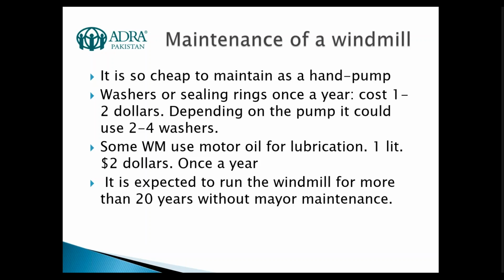And also the windmill can last more than 20 years without major maintenance. And the maintenance can be done, as we say, by the community as well. It's very, very cheap to maintain one of these windmills. Maybe from time to time only painting the windmill if the material is not galvanized. If it's iron, you can paint from time to time to cover the rust. But that is all we need to consider for the maintenance of the windmill. We can say it's the same maintenance as the hand pump, but the production of water is very different.